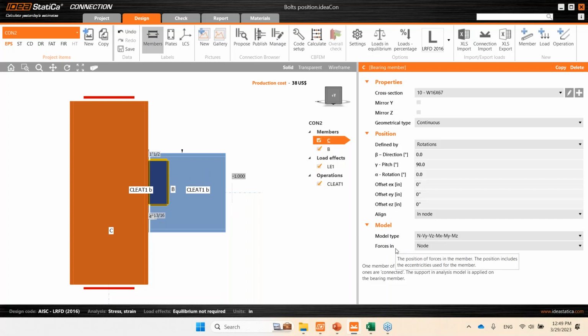Regarding the export from Risa through Excel, for the manual load input via Excel from Risa, did you determine that the positive or negative direction of the forces are consistent between Risa and IDEA StatiCa? Yeah, well, you'll need to double check that.